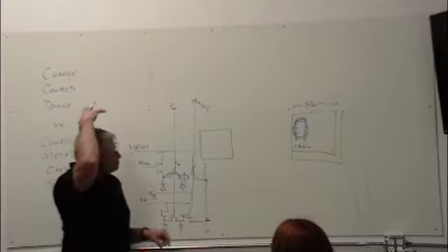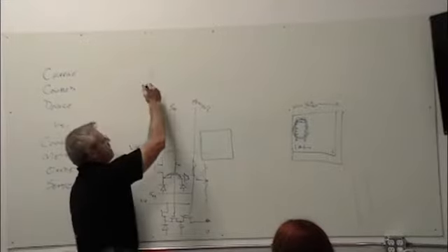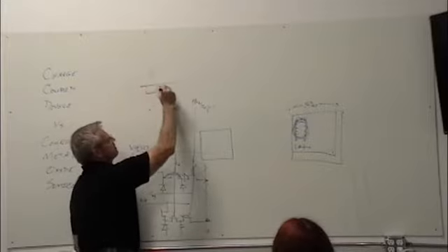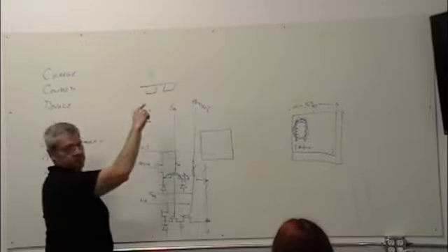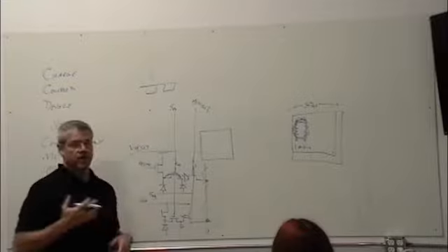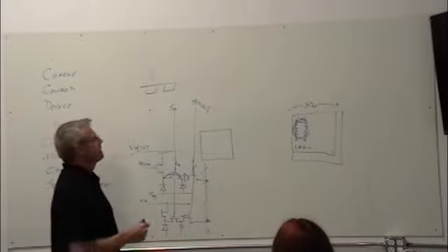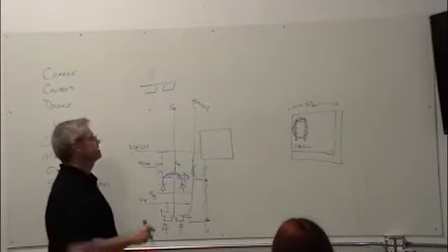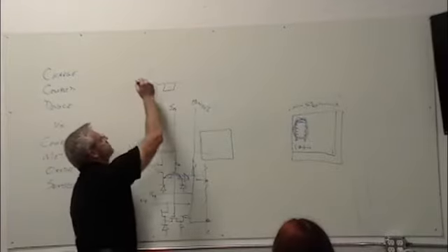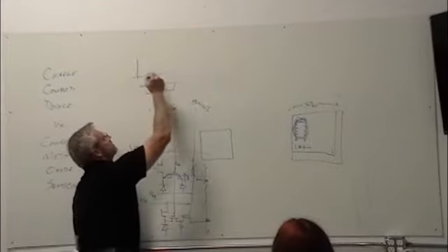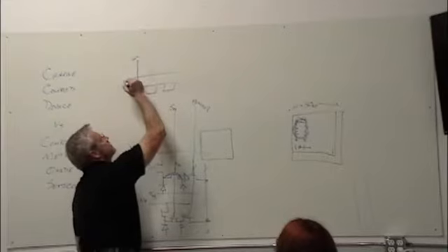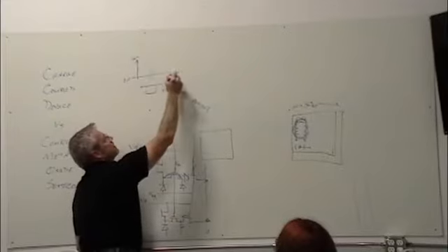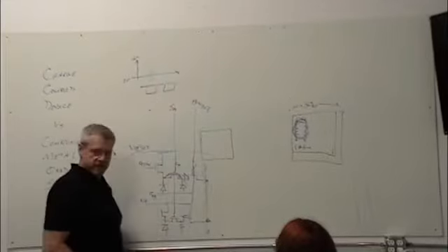So I didn't talk about blooming. On a CCD, I've got these little packets. So I say it can hold 150 electrons, right? And truth is, generally they hold 40 to 50,000 electrons. What happens is if you look at your signal output versus input, it is very straight.